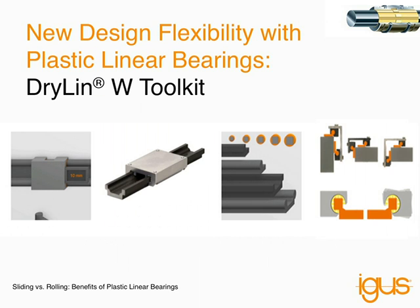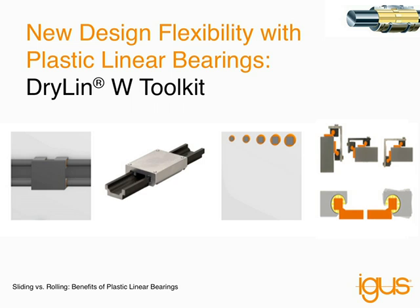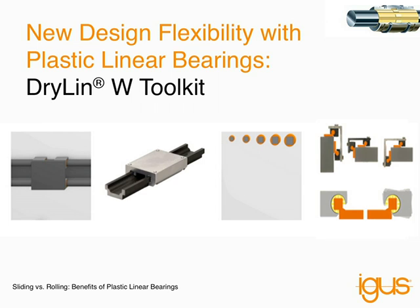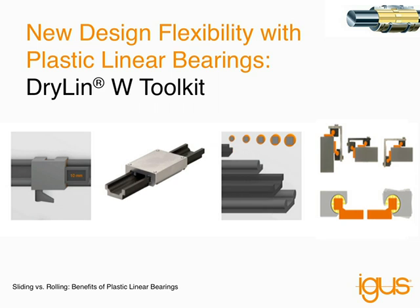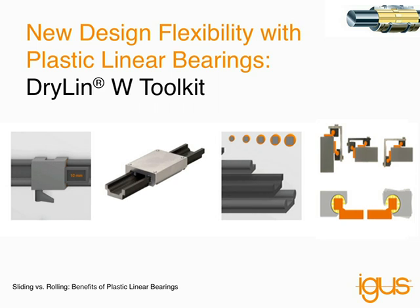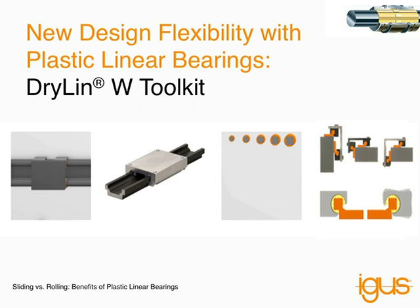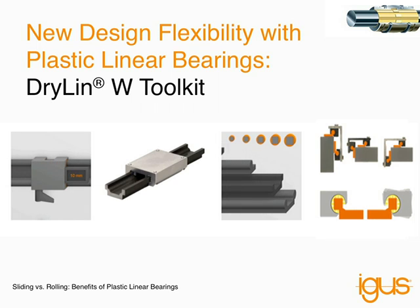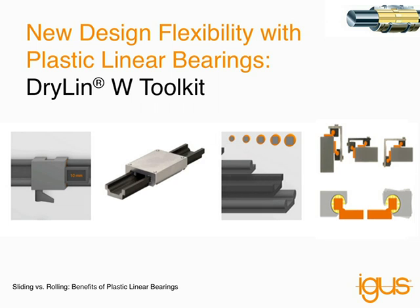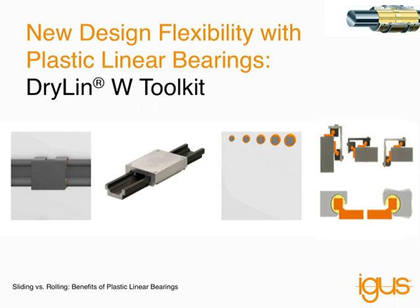One way igus has come up to help you free yourselves, for lack of a better word, from this existing technology, we've simplified into what we call our DryLin W Toolkit, which is basically a series of different types of modular rails and bearing assemblies, from single rails to double rails, that offer you complete flexibility in how you assemble parts to your system. So we have double rails, which eliminate the need for alignment, and we have single rails, which allow the flexibility for you to space the rails however far apart you require for your application.